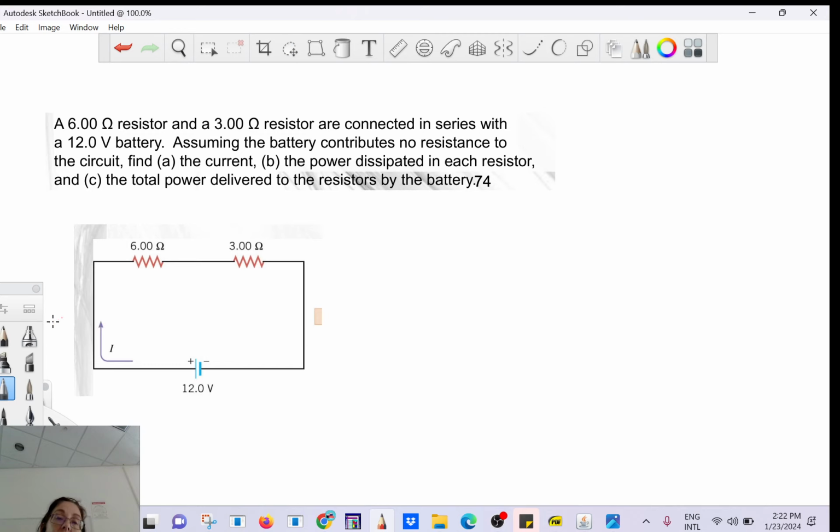So I'll show you one way to solve those problems. First of all, you start with the power supply. You start here, you follow the current. Oops, 6 ohm. So you make a 6 ohm there, and then keep going. Oh, a 3 ohm. So I make a 3 ohm here, and you go back to base. I call that my ground.